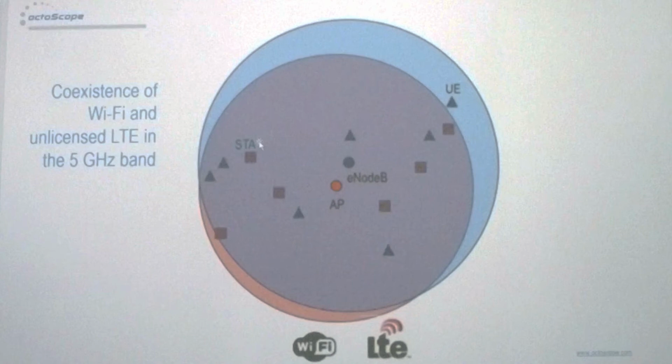And because LTE does not do contention, it does not do CSMA/CA, does not do collision avoidance, it will jump in and transmit for periods of time without backoff. You can use, for example, our iGen or PAL to generate interference without backoff if you wanted to simulate it. And you can set the gap between packets to control how often it goes on.